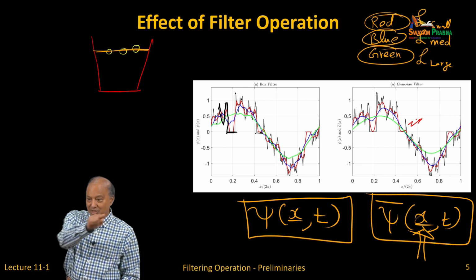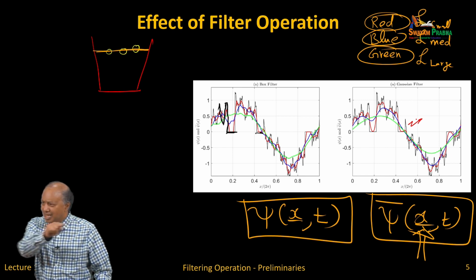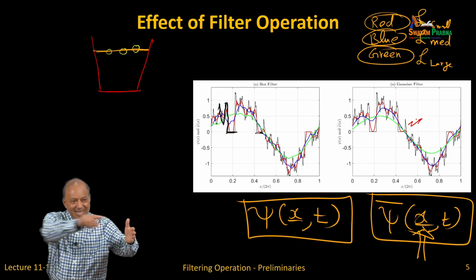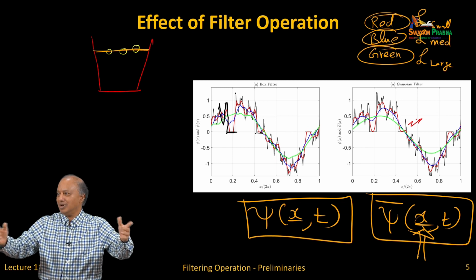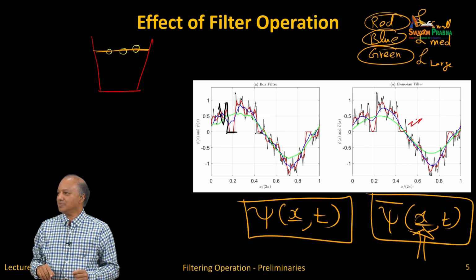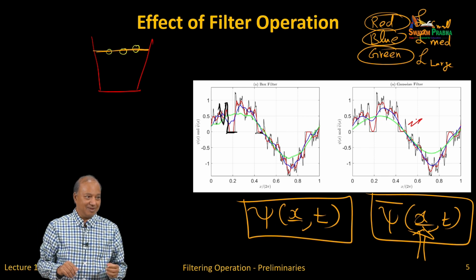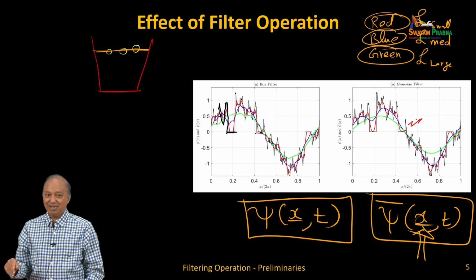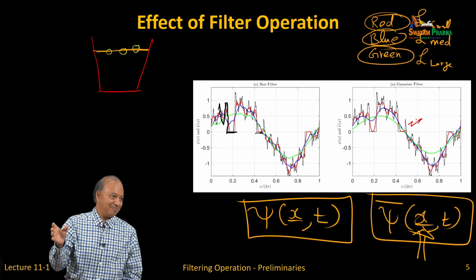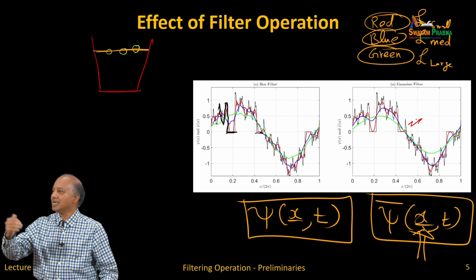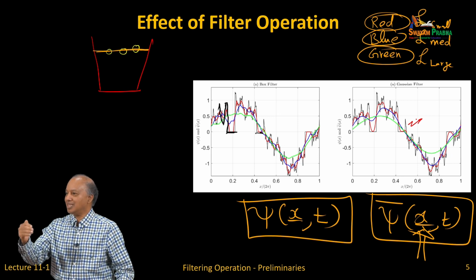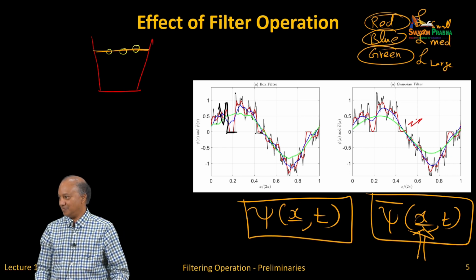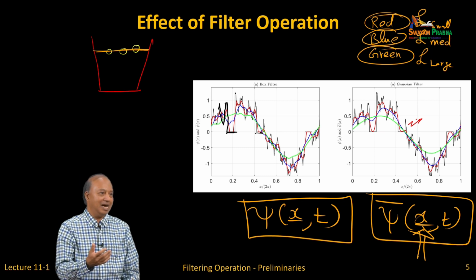So in other words, the way to think of this, I'm taking a horizontal cut section, say from one end of the bucket to the other end of the bucket. I've taken the velocity at one realization. And I repeat this experiment again. Now, that will be another slightly different black curve where there may be particles somewhere else. And you collect 1,000, 10,000 black lines, and now you average it. That's what you're doing in ensemble averaging.